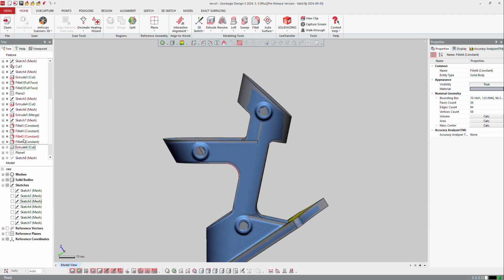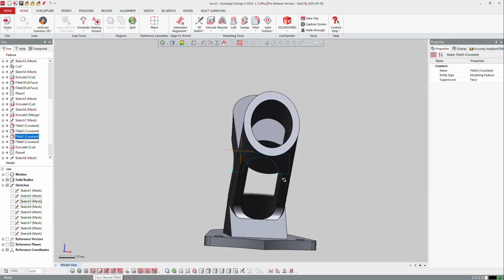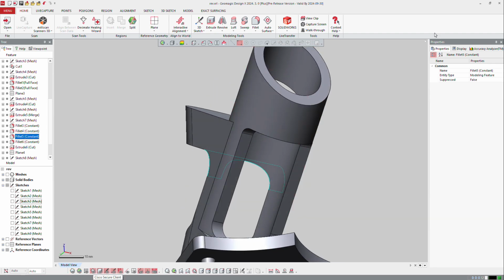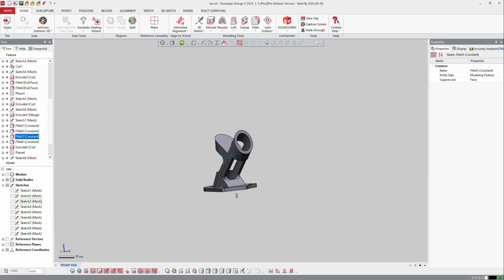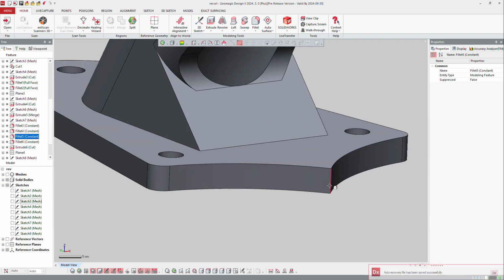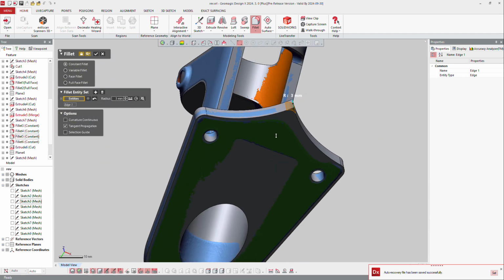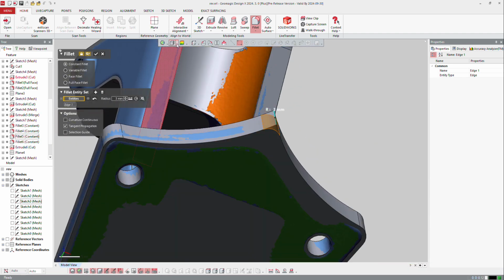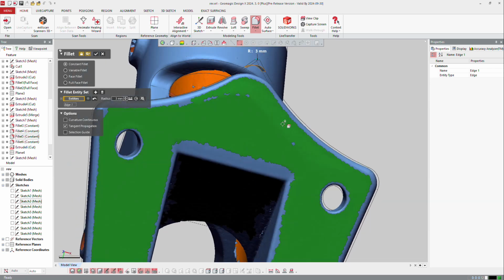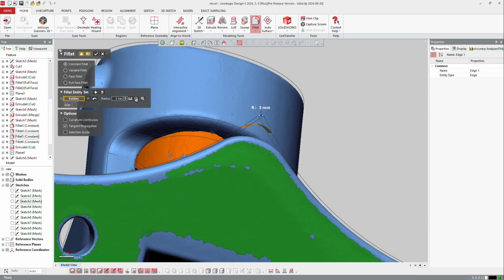All right, so now I can go back to the end. So right mouse click, roll to end, and the software reproduce everything here on the part. Now, as at the beginning, I said I want to make that edge at the end, right mouse click here, fillet. I can always display that shape and ask the software to display my CAD in transparency here, and I can see now the fillet. I can estimate the fillet.